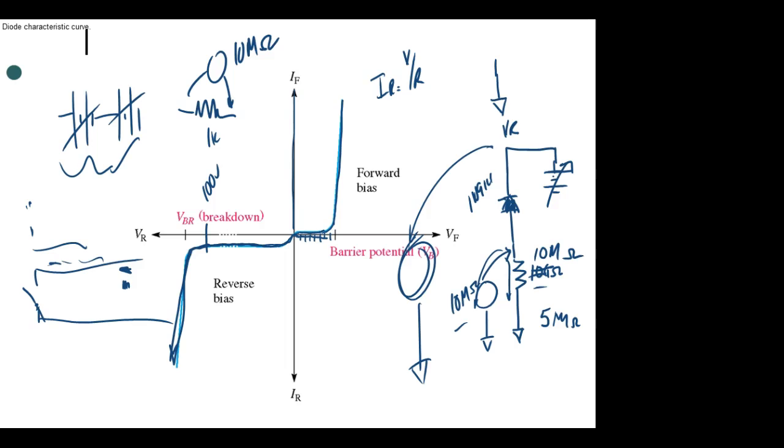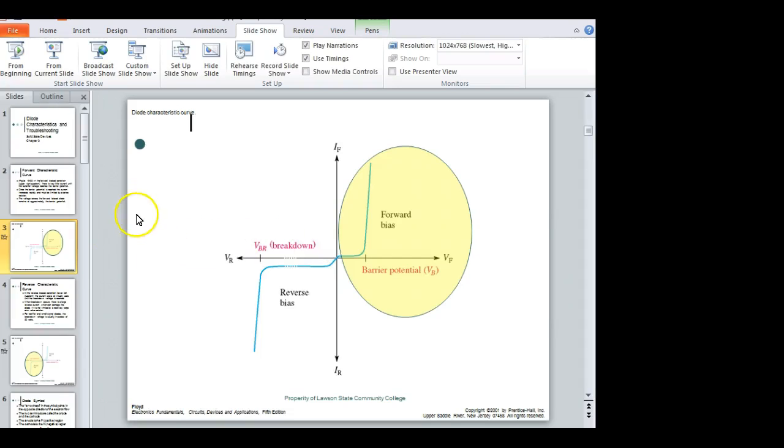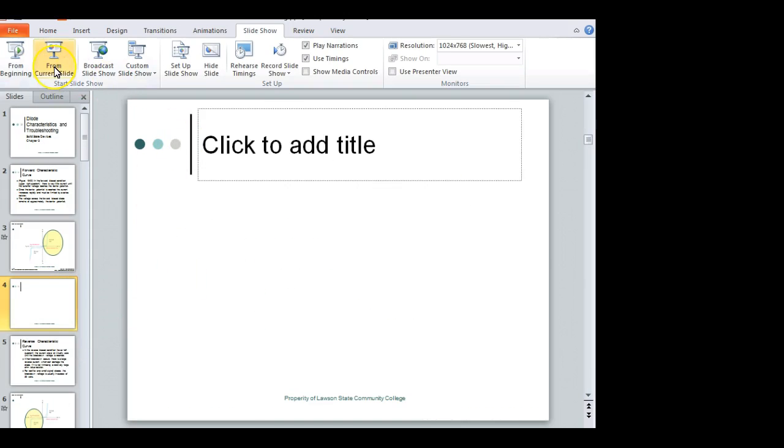Now, what we're going to have to do, and this is in my book, so when I give you all the lab procedures, it's going to tell you before you start a lab what you need to do. Come up here and do the modifications in your book, because I don't remember all of them, right? Now, the problem we have with our variable supply is we're going to have to bring this thing down to 0 volts. It's almost impossible for a variable supply to put out 0 volts when you turn it down to minimum. So what are we going to have to do? We talked about that in the other class. Y'all remember? Nobody remembers.